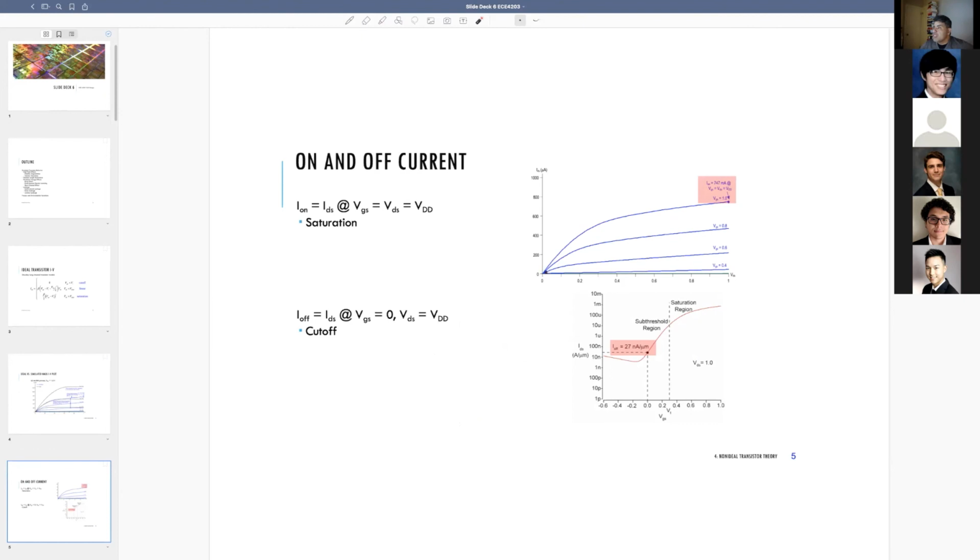So again, this is like redrawing the same curve when the device is on. Remember, in a CMOS transistor, a CMOS gate, when the device is on, the gate-source voltage and drain-source voltage are both going to equal VDD. When the device is on, we put a logic 1 on the gate to source, and so it looks like the supply voltage, VDD, and the device is either pulling fully to ground or fully up. So you end up in these regions a lot when the device is on. In those cases, your on current ends up being less. Plus, to get there in a transient way, you follow a weirder curve.